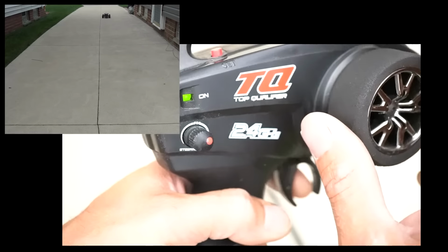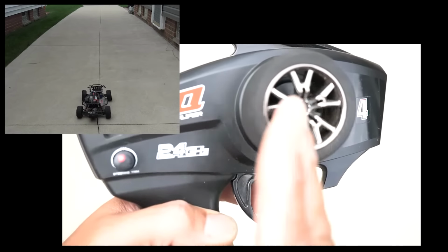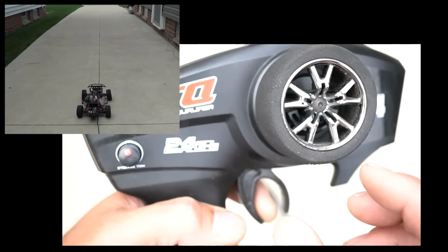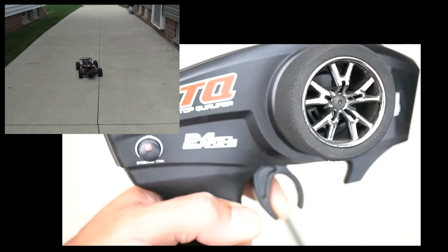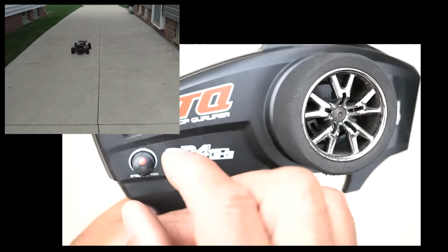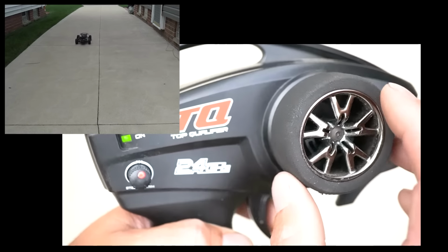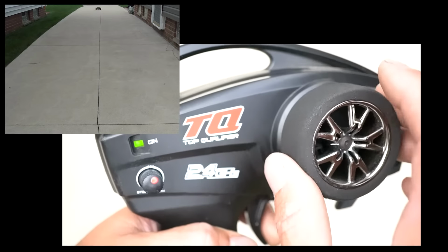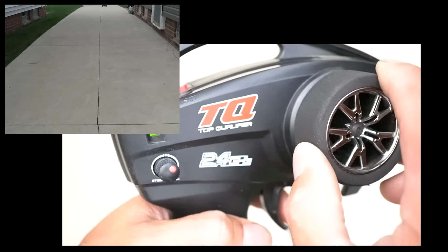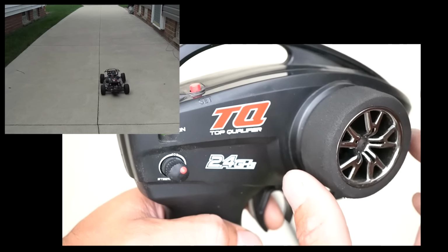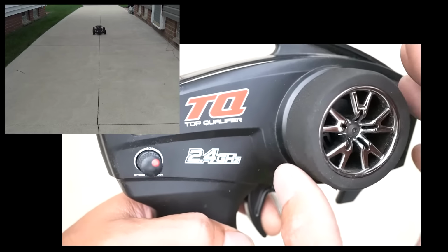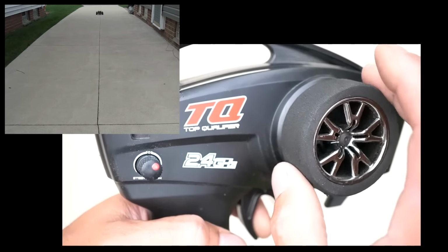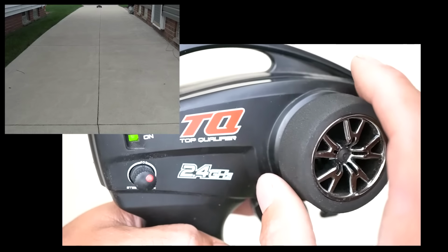All right, I think it's safe to say that in a perfect world, with this trim at zero and this wheel centers itself, this would be zero short term and zero long term. As I start to go here, you can see this vehicle's pulling hard to the left. So I have to add some right long term, because I gotta keep on adding this right short term all the time. I get tired of adding right short term. I gotta add some right long term. Now when I go, I have less of a correction for my short term. I'm just tapping this wheel and we're going pretty straight. Still a little bit to the left, so I want to add some right trim.